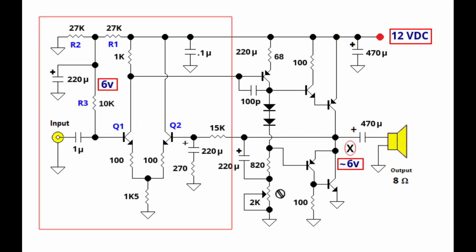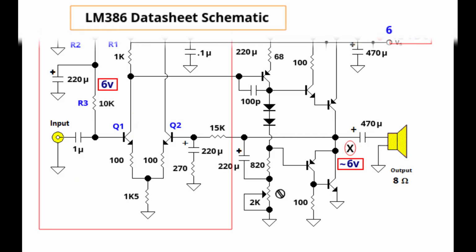So we have the output of the amplifier getting negative feedback to the input of the amplifier through the base of Q2. In summary, for the Q1, Q2 emitter coupled pair, each of the bases of the transistors gets approximately 6 volts DC bias. Q1 receives the audio signal input, and Q2 receives the negative feedback from the output. This is typical for most integrated circuit Class AB audio power amps. In fact, it's how most op amps work as well.